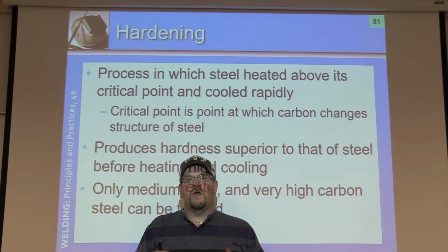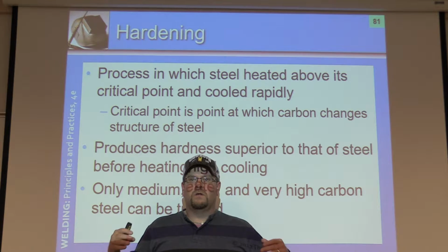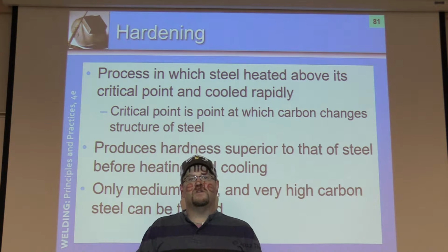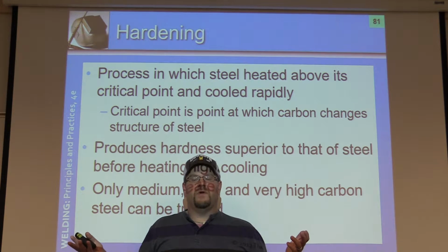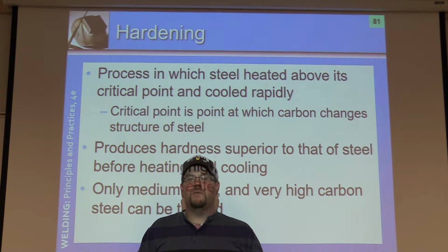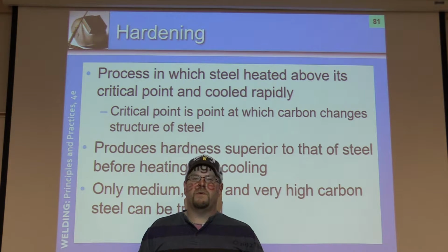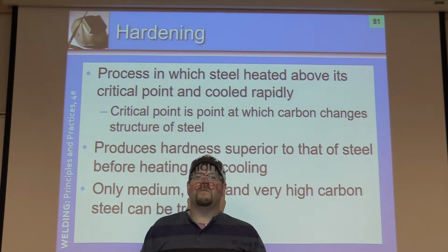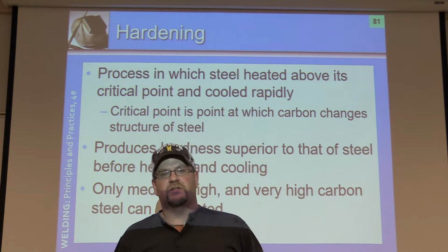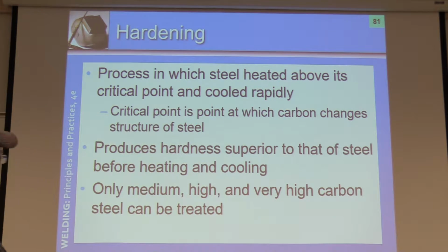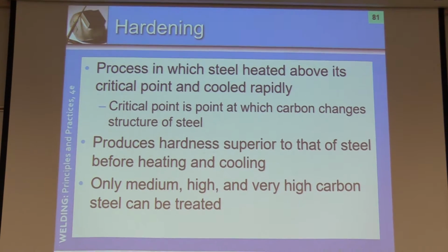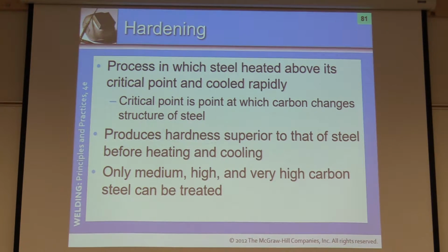They were all out of the same piece of steel, and when we pulled them apart to do a tensile test, there was roughly 35 to 40,000 pounds difference, even out of mild carbon steel. A lot of times I'm a prove-it type of person. If I have the equipment to do so, I will try to test it just to see what I can get. All right, we're going to go through this.